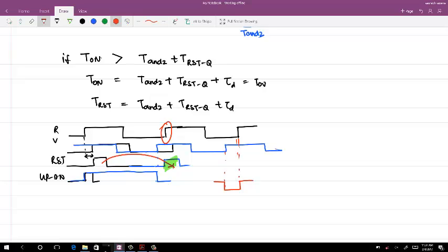Okay. So because of a finite reset time, when you are close to the phase error of 2 pi, you actually miss the transition in this kind of phase frequency detector. And when you miss the transition, this will then continue in all the consecutive next cycles, so that your phase error actually becomes negative.